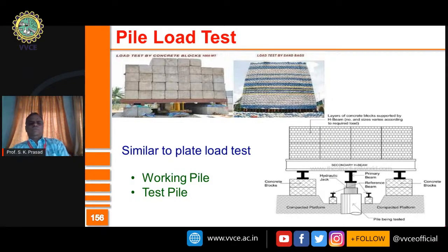You know, plate load test is carried out to find the load carrying capacity of shallow foundations. Very similar to that, pile load test is carried out to determine the load carrying capacity of piles. So conventionally, just like plate load test, you're going to apply more and more load. There is a base plate at the bottom, and there is the pile which is put, and you keep on applying the load either until it fails or until the